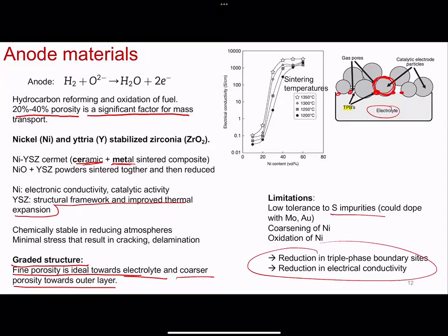The more complex your compound becomes, with all these small changes in stoichiometry, that's fine. You can do a lot of engineering in terms of, okay, if I dope in this and I dope in this, your phase diagram becomes really complex, because what tends to happen is you add in more elements, the complexity of your phase diagram increases, and chances are you're going to stabilize the binary oxides as well.